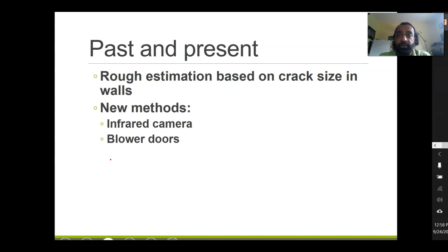We can use blower door testing, which is basically sealing and closing all the windows inside the house. You put in a blower door, which is a door that has a big fan in it that will create a vacuum and negative pressure, and you can go with a smoke test around the house and see what areas leak the most. It's very difficult because you cannot see air, and a small draft, if it's not windy, is really hard to detect. So it's good to have a good method to detect where the leaks are.